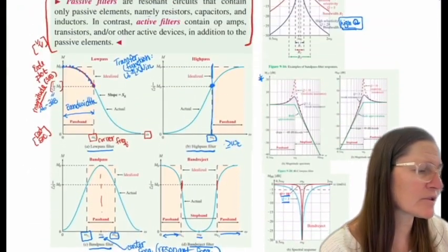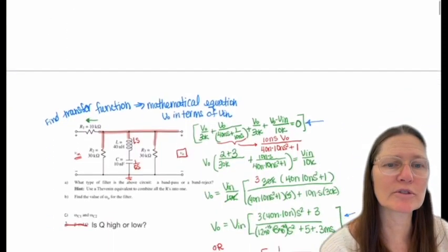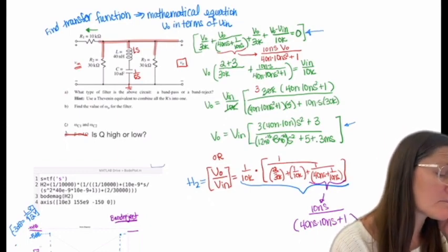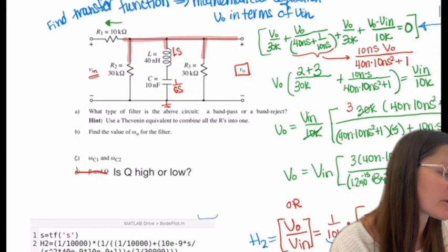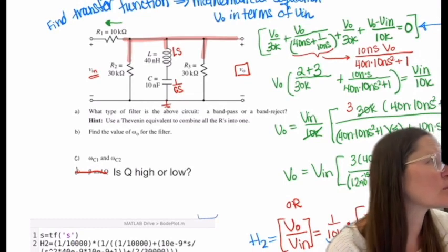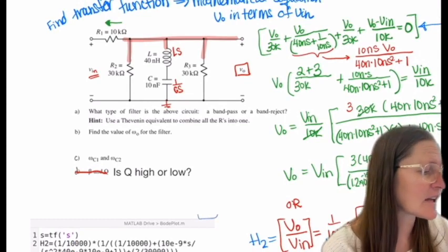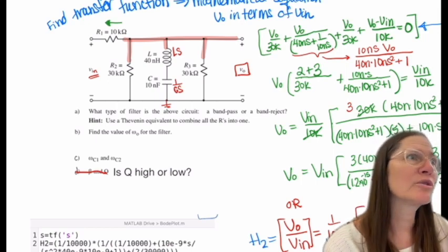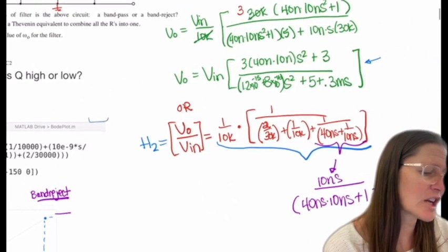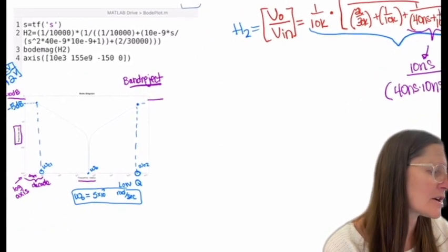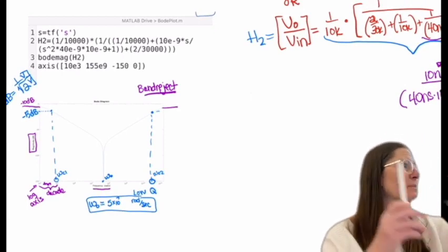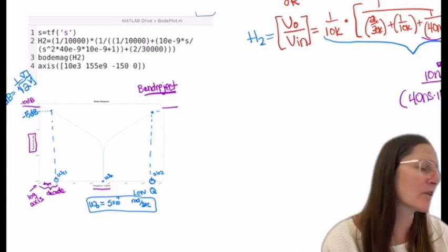All right, any questions about the filters and what you need to know for filters? Okay, so from there we went into finding the transfer function. To find the transfer function, we no longer need to find that initial value. So you can do it with just 1 over CS and LS for your inductor. You solve to find the transfer function, which is output over input. And then from there, you can change from S's to j omegas to convert back if you want to do the Fourier transform, and that will encompass both the initial values. So that's the whole methodology.